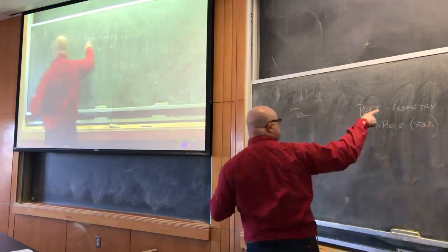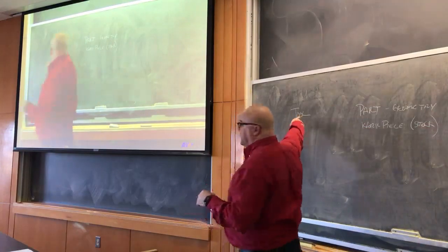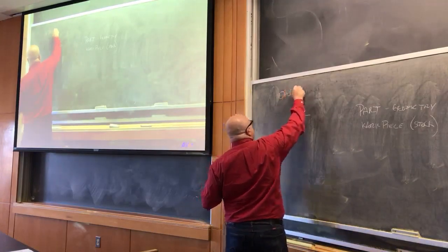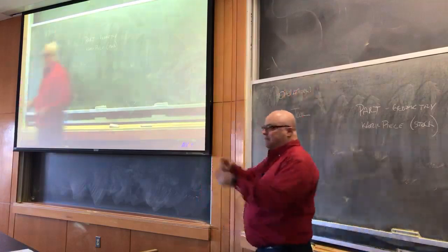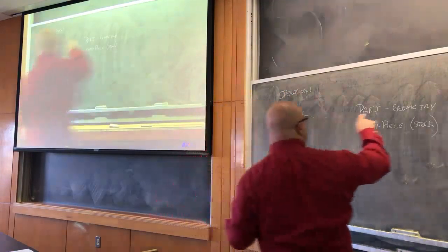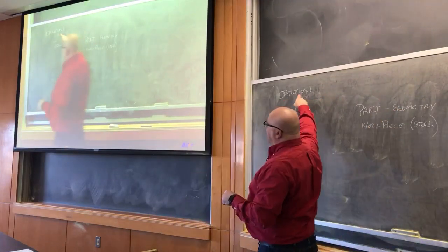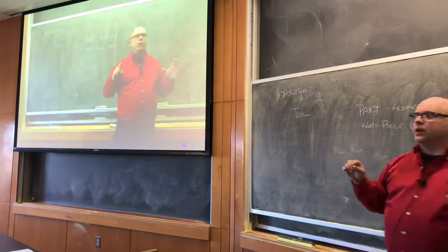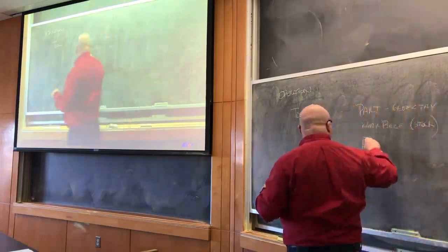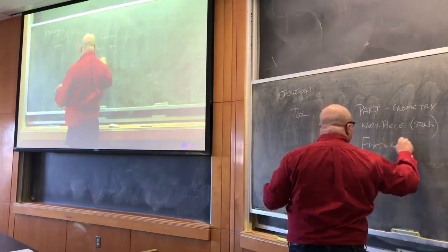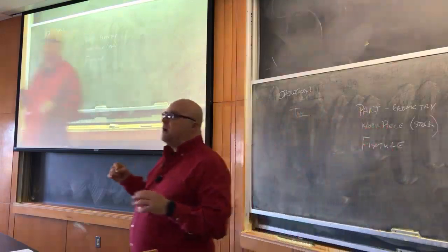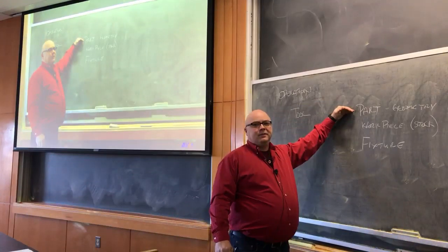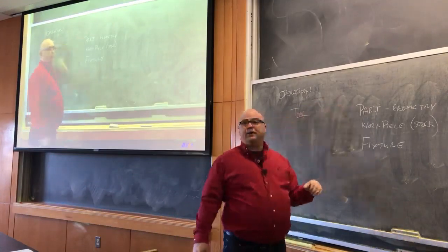All right. Once we know this and we know this, we can start getting into tools, and we've chosen our operation. I was supposed to write all that stuff down before I asked you that question. Part geometry, workpiece, stock, operation. Actually, I think at this moment, we also need to understand our fixturing. Now, I know people don't always do it in this order, but if you haven't figured out what it is you want to make, then you have no business picking out tools for it, right?